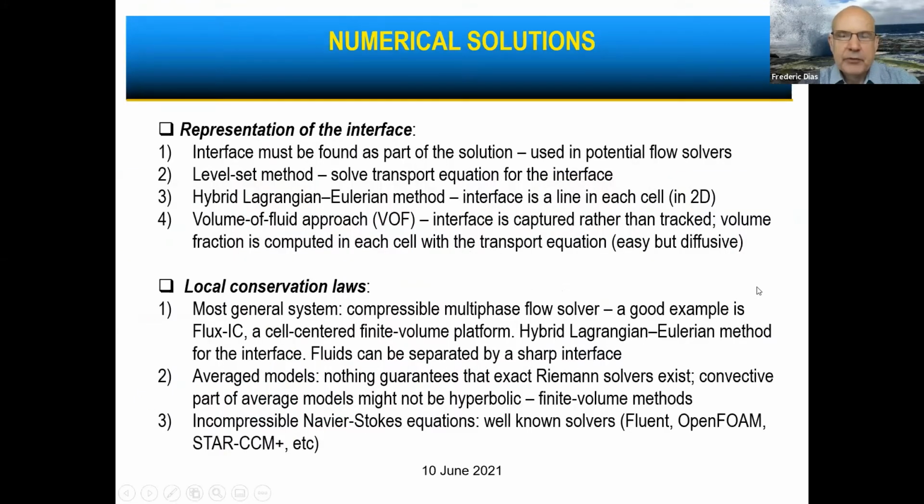So now talking about the numerical solutions, essentially, how do you represent the interface? And here I put four ways to do it. The interface must be found as part of the solution, which is used in potential solvers. The level set method is one option. The hybrid Lagrangian method is another one, and the volume of fluid approach is a classical one. It's easy, but diffusive. Of course, this is a brief summary, so one has to be careful to generalize, but that's the overall impression.